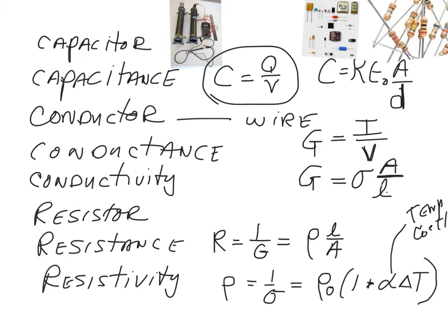And so every material will have an intrinsic, say aluminum. It has an intrinsic resistivity, but that varies with temperature. And if we want to know that, we have to know the temperature coefficient. And the rho naught means the rho at room temperature. It doesn't mean the resistivity at 0. It's usually measured from room temperature, which is generally taken to be 20 degrees Celsius. So these are the equations that we're going to use this week to solve the problems in the assignment.